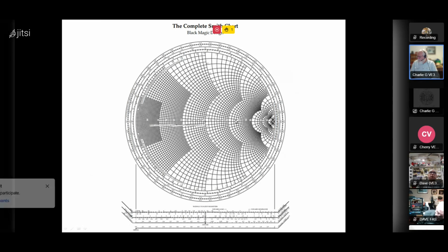Yes. See if I word this correctly. When we were doing probe measurements, we discovered that the accuracy of impedance, I think, wanders once you start getting close to a K, or certainly above 500 ohms, that kind of thing. But it made me think of this when you were saying on the right side of the Smith chart, you're at infinity, and the left side, you're at the short. So that means if we had 50 ohms in the dead center and you're at infinity to the far right, how accurate is it when it's halfway between? Like when you're up in 10K, 20K, and 1 meg and stuff like that.